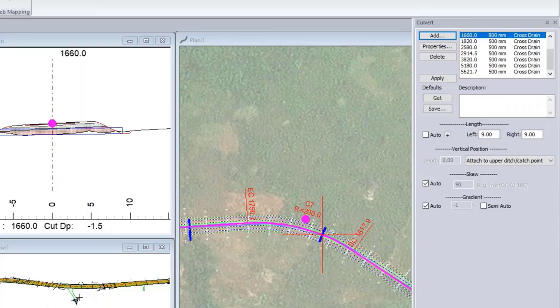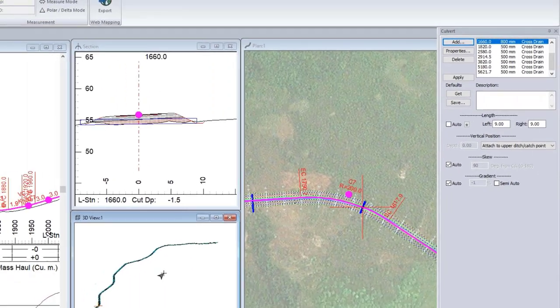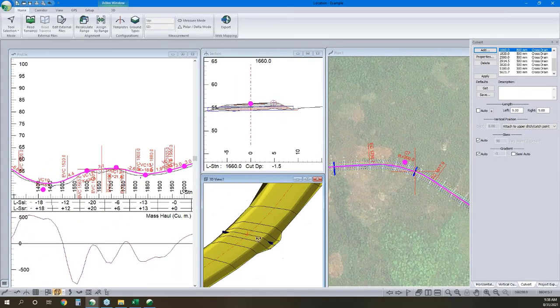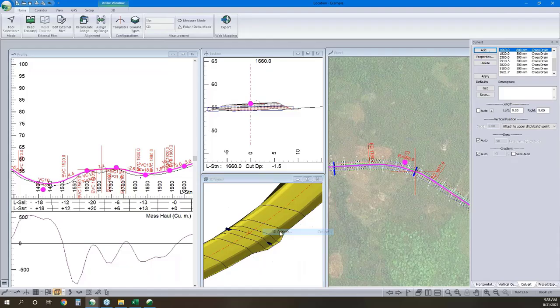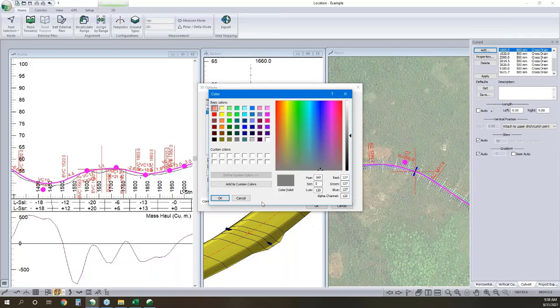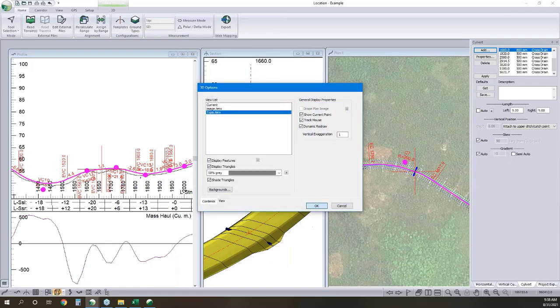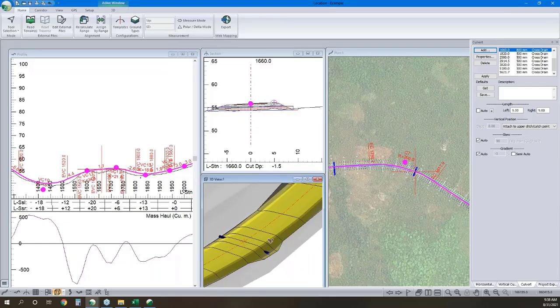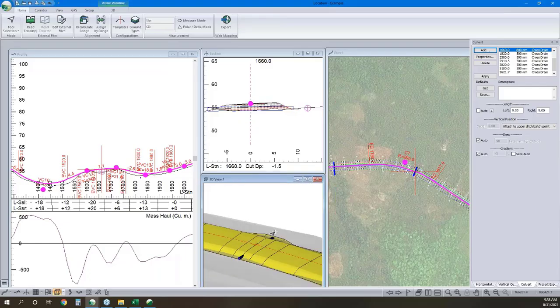Another thing that I do use a lot for culverts is the 3D view. So we can see where that pipe is positioned, and if we had this set up to include our topo surface. If we had a surveyed feature or whatever for a draw, we could really line that up and get a perfect match for the existing ground. We'll come back to the next question there.